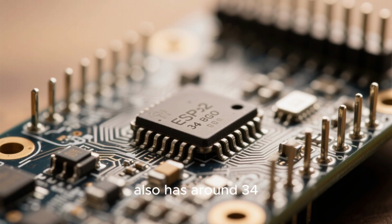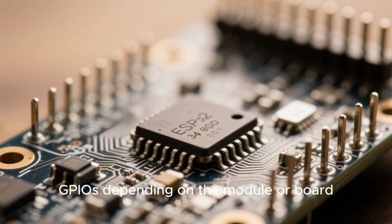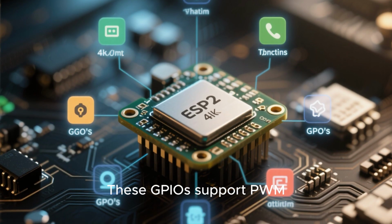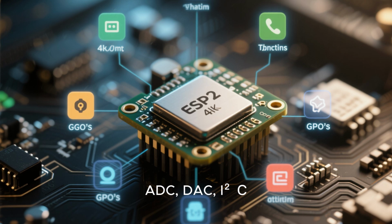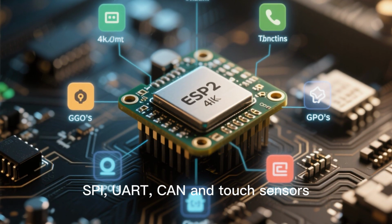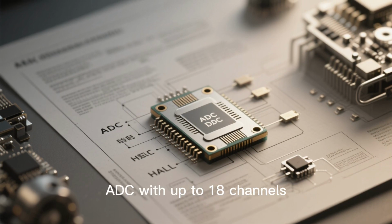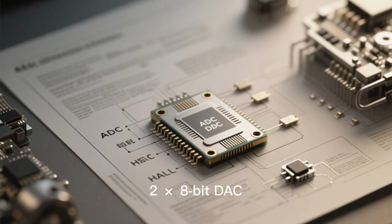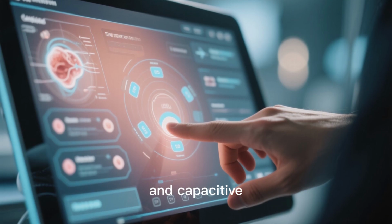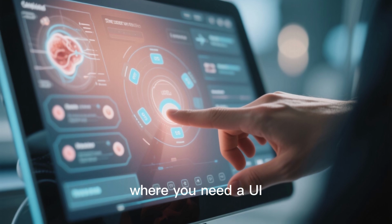The ESP32 also has around 34 general-purpose input-output pins, GPIOs, depending on the module or board you are using. These GPIOs support PWM, ADC, DAC, I2C, SPI, UART, CAN, and touch sensors. Additionally, it has other features such as a 12-bit ADC with up to 18 channels, 2 8-bit DACs, a built-in Hall sensor, and capacitive touch sensors, which are ideal for biomedical applications where you need a UI.